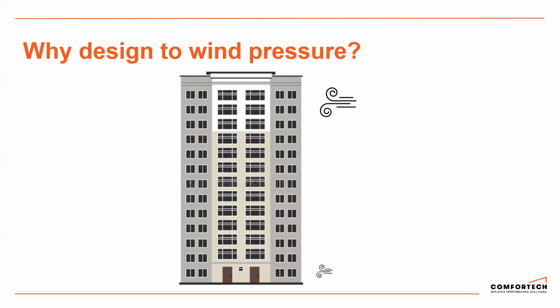And there's a big difference between what the wind pressure is on the ground floor versus what the internal wind pressure is going to be 50 stories up. If you can imagine you're opening a sliding door or a window 50 stories up, there's an awful lot more wind that's going to be hitting your internal partitions, possibly causing those steel studs to deflect.